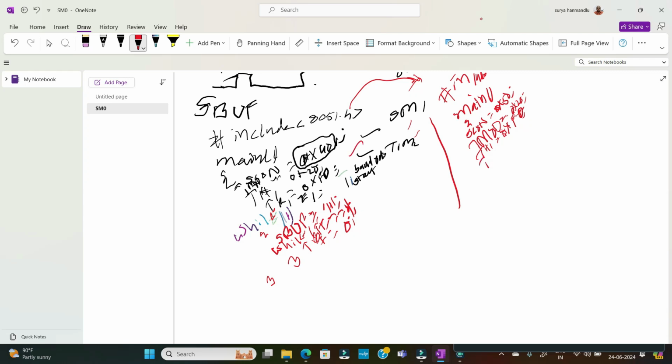And here also we have to start the timer. To start the timer, we have to set the timer 1 run control bit, and we have to terminate the statement, same like here. Okay. And again, we have to take a while 1 loop.